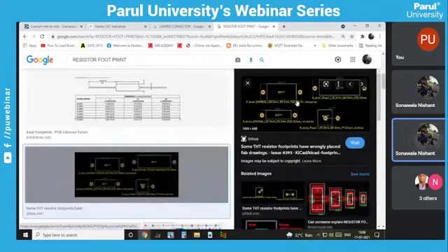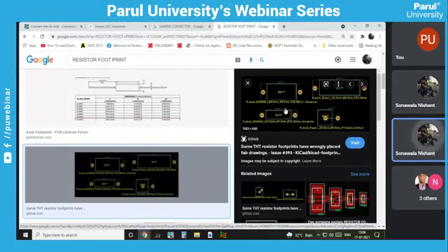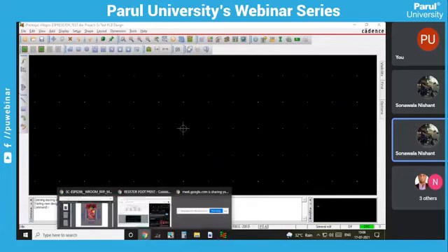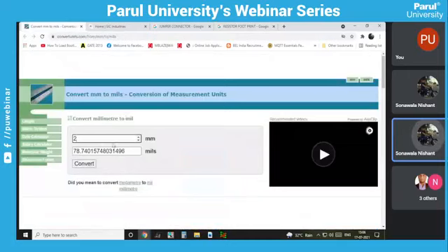So here we have the reference. Now we are designing the footprint for the resistor. Here we have already mentioned, we have given 5 mm of distance. This whole software is working in mils. So first of all we are converting that 5 mm to mils. It's 196 mils.